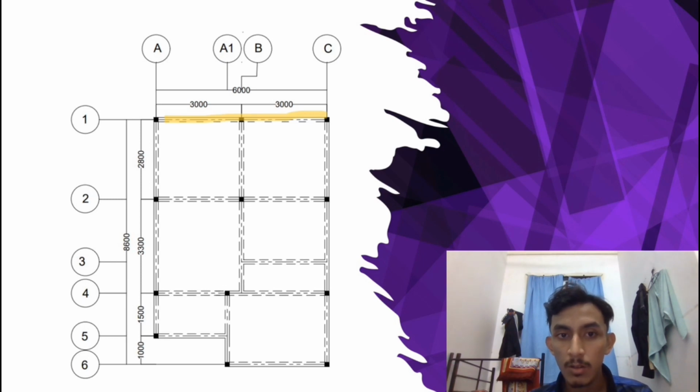The maximum shear force and bending moment at span A to B are 34.62 kN and 19.91 kN. The shear force and bending moment at span B to C are 56.61 kN and 19.76 kN.